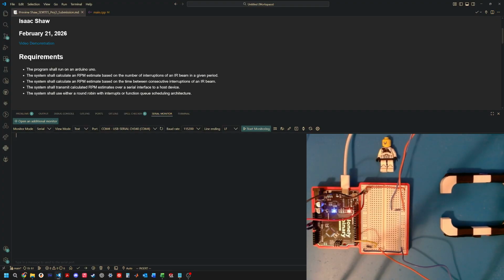For convenience and or safety, I have the LED and photodiode in a 3D printed mount that lets me keep my fingers away from any spinning objects and keeps things a little more consistent and predictable. Keeps the beam aligned and the spacing consistent.